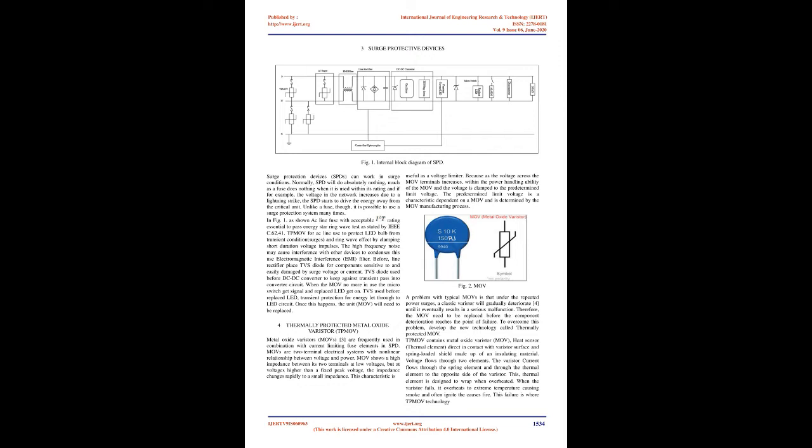Upon varistor failure, TEEP MOV technology prevents the varistor from excessive overheating and thus prevents the possibility of dangerous smoke and fire. When the varistor fails and heats up, the thermal element heats up and warps, which causes it to release the arc shield. As the thermal element releases the arc shield, the springs push it upward, causing the shield to cover the varistor and prevent any current flow from the thermal element to the varistor. This prevents the varistor from continuing to overheat and cause smoke or fire.